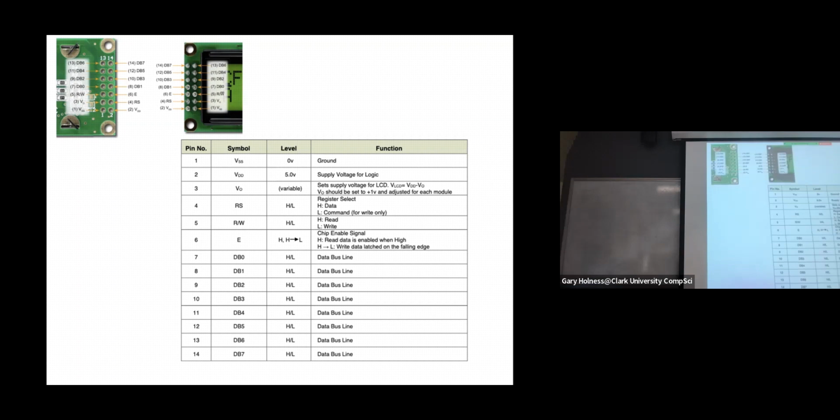That means whatever appeared on the data bus will physically be written. So that enable is really a clock signal. It's how you force the device to actually step through the sequence of operations you've selected, the opcode, in order to carry it out.